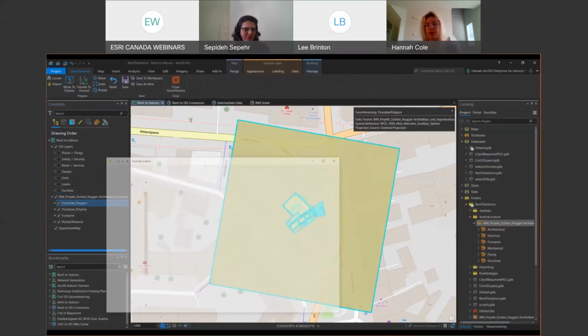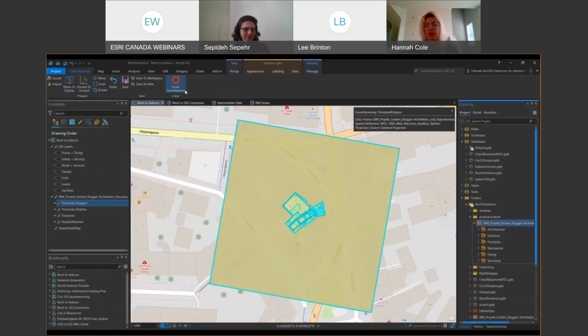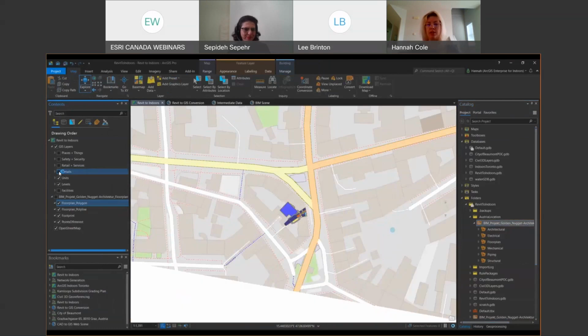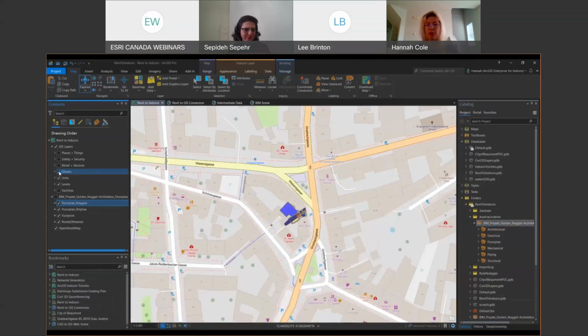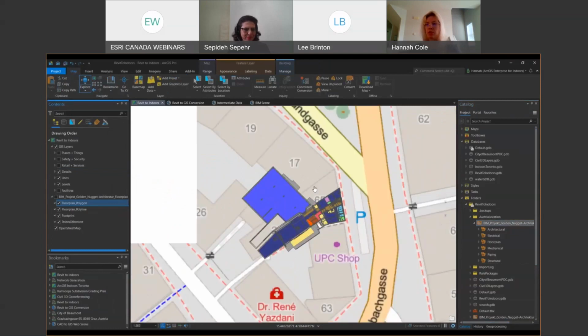In the case of our demo today, I've been using a little bit of ArcGIS Enterprise, but focus in ArcGIS Online. You can georeference a Revit file in a 2D map or in a 3D scene. This data must be georeferenced, however, before it can be worked and analyzed and mapped further. If you're working in a local scene with a geographic coordinate system, you must convert it to a global scene before publishing.